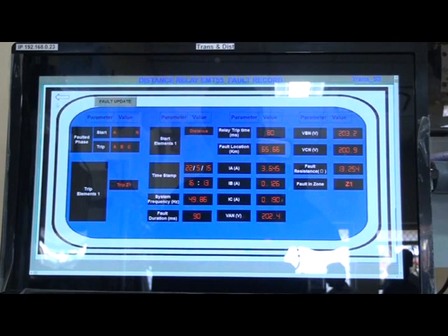We observe the timestamp date, that is 22/5/2015, time is 16:13, and fault location is 66.66 kilometers. Similarly, you can observe other faults like line to line and line to neutral also. These relays are supplied to various electricity boards all over India. Hence students and research scholars can get experience with relays at the academic stage itself.